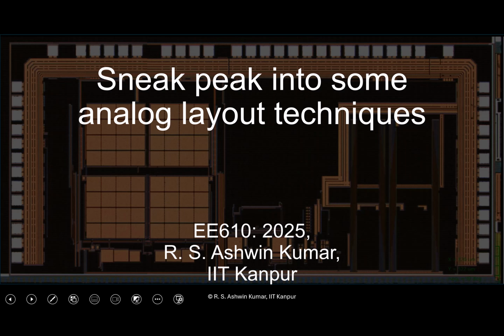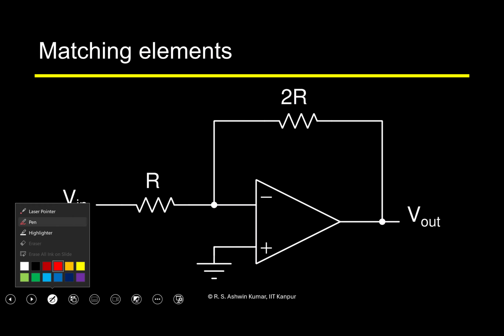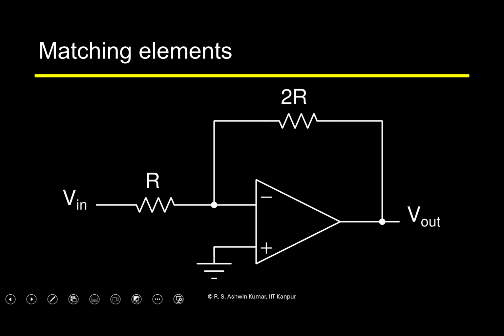The first thing you have to do is something called layout. That is where you become a civil engineer and decide where each block is going to be placed and how connections are going to be made. Let me give some tips as to how to do layout. Doing layout is not a really great value addition, anyone can pick it up at any point, but what is important is how to do good layout. So that's what I wanted to briefly talk about.